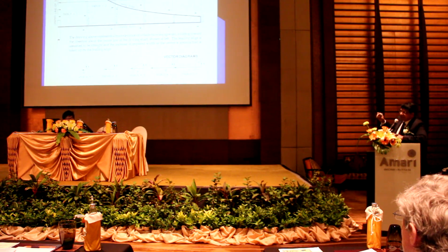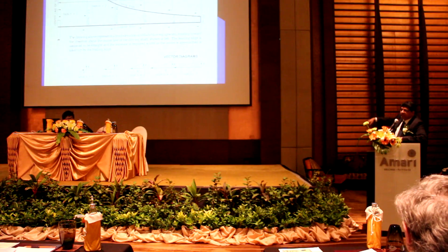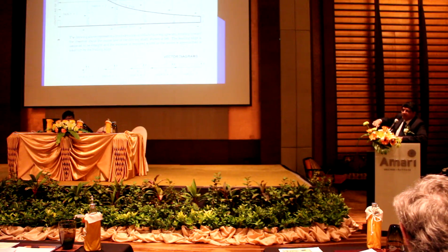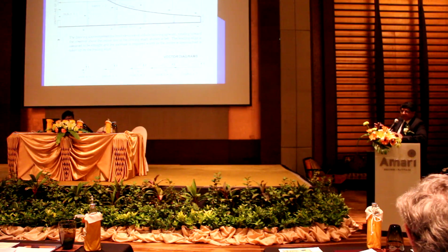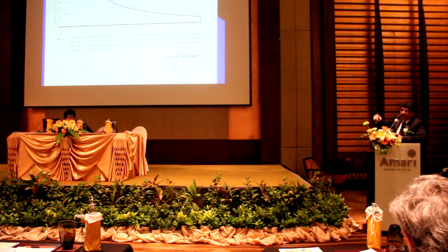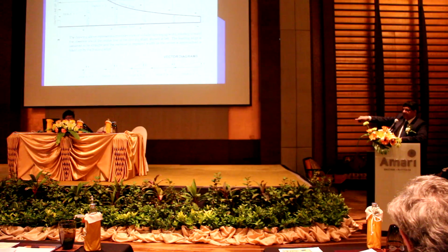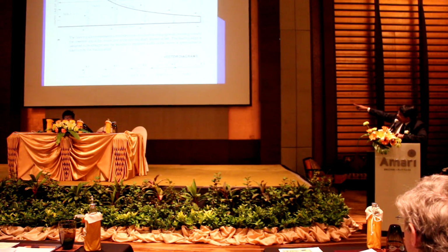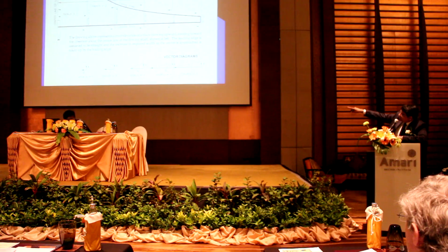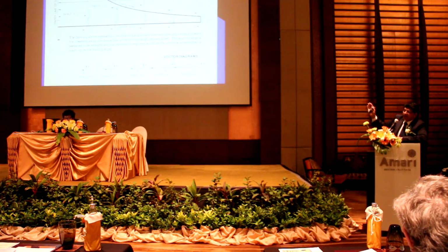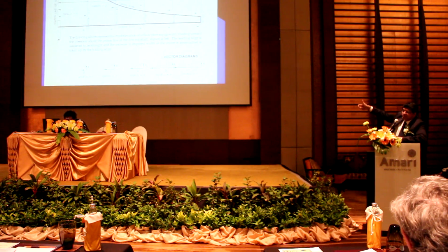As you can see, the tip runs faster, whereas closer to the hub it runs at a lower speed. It's simply the circumference multiplied by the RPM. So obviously at a lower radius, the aerofoil moves at a smaller speed. In the same blade, at the tip portion, it moves at a higher speed. So as you can see, to maintain the same V, because the speed is lower, I need to have a higher angle of attack, which means the blade has to be twisted quite a bit.